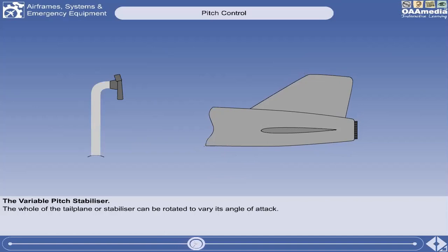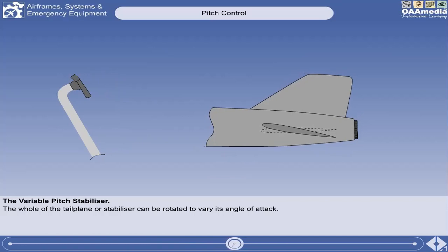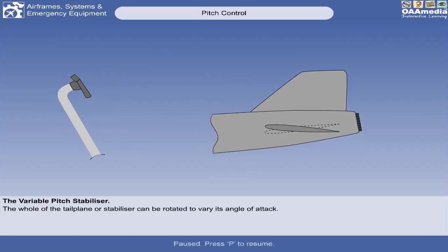If the yoke is pushed forward, the leading edge of the stabilizer moves up and the trailing edge down. Okay, ganun din naman, although kanina kasi elevator lang yung nag-deflect, no? Either up or down. Dito naman, yung entire stabilizer na yung gumagalaw. Okay?